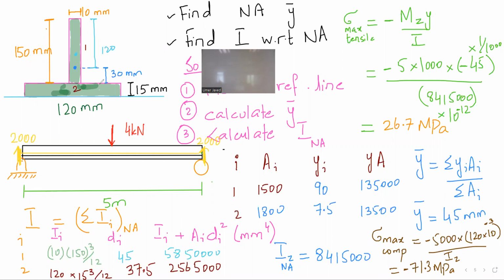The polar moment of inertia that you are taking, you will take by having... Is this solid? Yes. So show me the polar moment of inertia. Pi c to the power 4 divided by 2. This is correct. Okay. Now show me T. This is 1.2723. Very good.